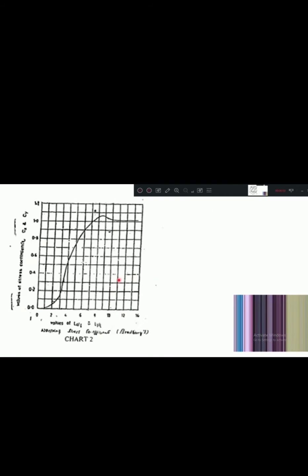So like this you can easily find the stress in kg per centimeter square. No need to calculate with the formula. Similarly, in case of corner, for a particular value I can refer to the inclined K values, and directly with the help of thickness you can find the stress in kg per centimeter square.